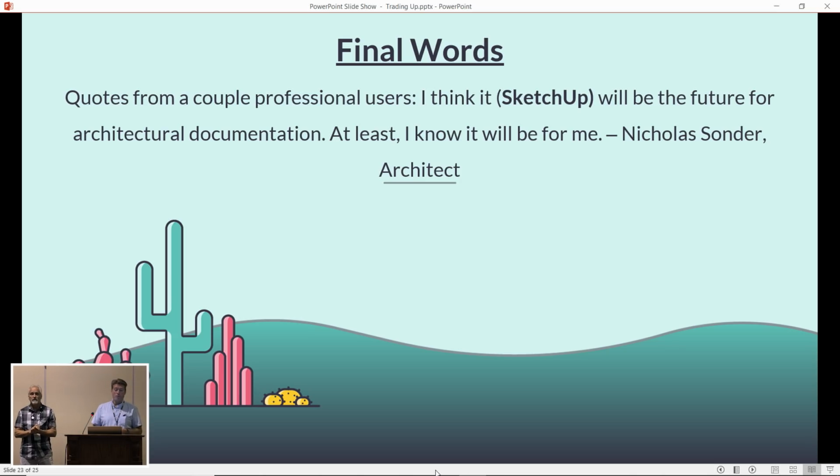As long as the dimension is connected to an edge or a point in the model. One of the things I do not do, and I think Nick doesn't do either, is dimension in SketchUp. I dimension everything in Layout. There are people that do. Some put their grids and some architects will put everything in there, but it tends to make a mess of the file. I think it's better to keep that SketchUp file as strictly the model, where you're doing all your design.